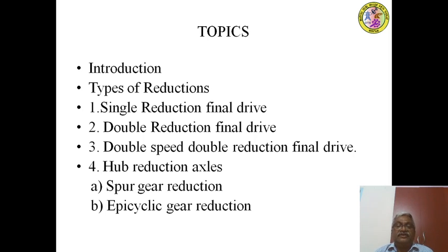This topic covers introduction to final drive, types of final drive reductions such as single reduction final drive, double reduction final drive, double speed double reduction final drive, and then hub reduction axles. Again in hub reduction axles, spur gear reduction and epicyclic gear reduction.